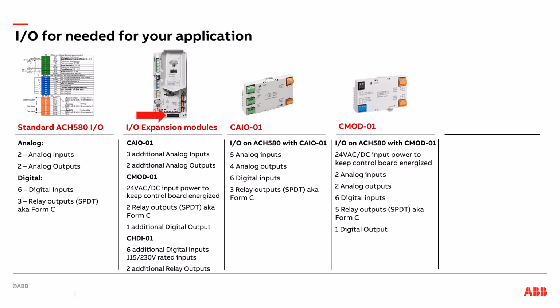the control board. If connected to a UPS system, in the event of an input power loss, both the field bus and serial communications will remain active. It also provides 2 additional relay outputs for expanded process control and a digital output if you need to communicate to pilot lights, alarms, auxiliary relays, solenoids, or a PLC digital input module.